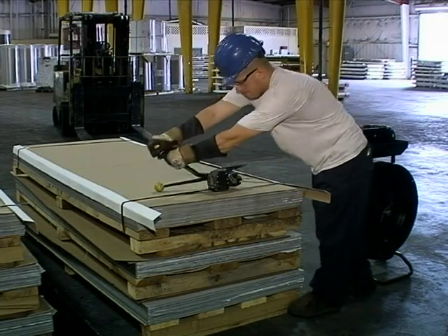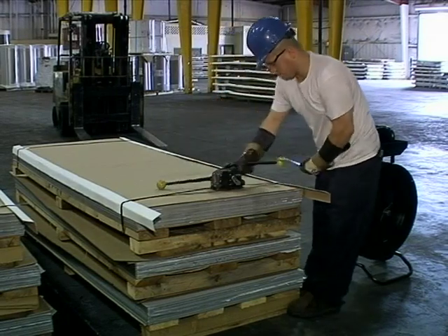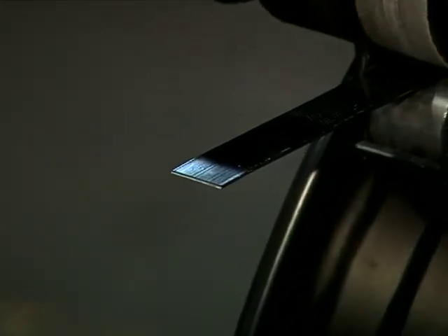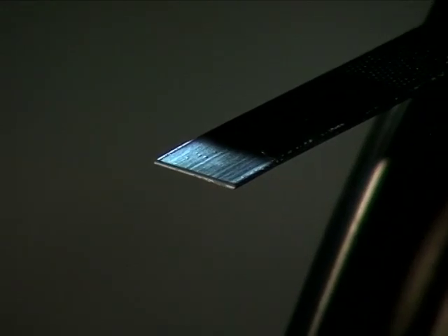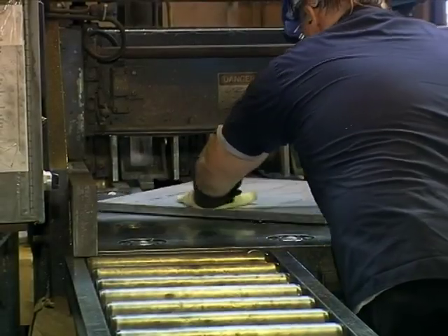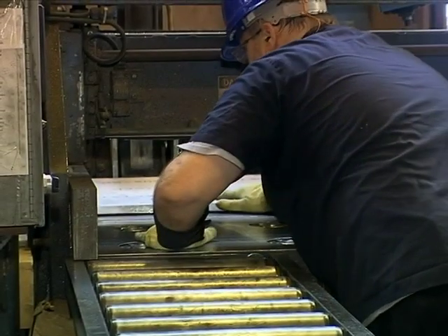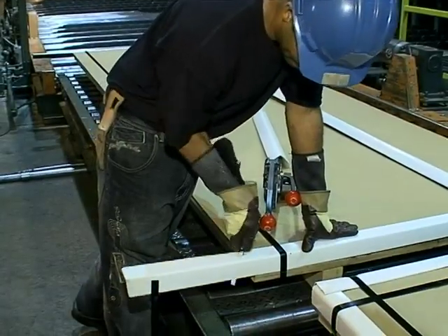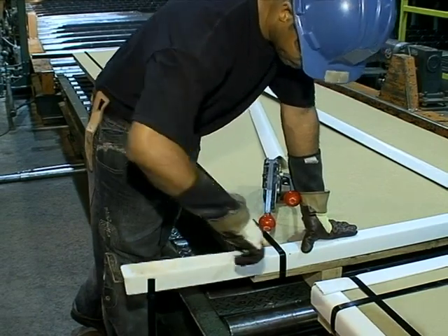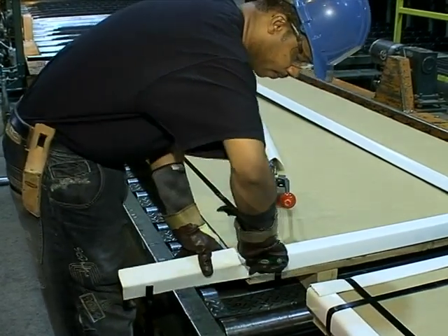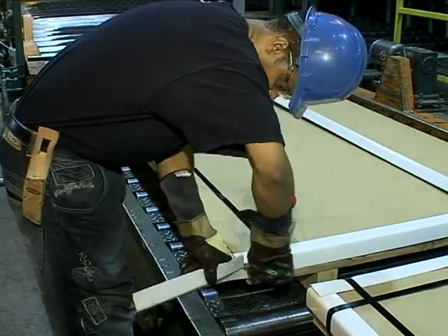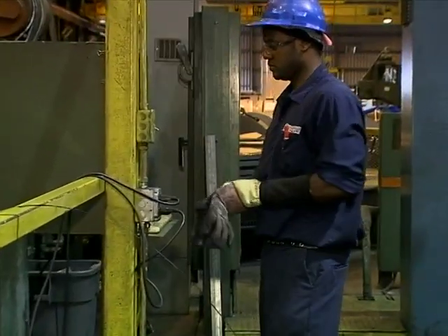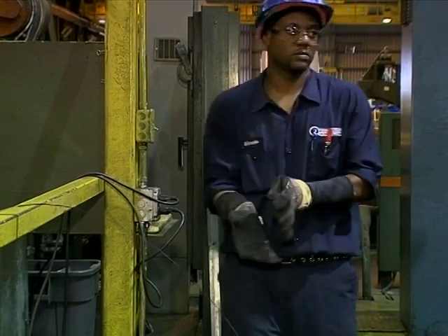Typically, the edges have been rounded by the manufacturer of the banding, but a razor-sharp edge is created when the banding is cut on the end. In addition, laceration risks are present when handling cut plate, long products, or scrap material with rough edges. Utility knives are commonly used on the job, and these too can very easily cause a laceration if not used correctly. If you are performing any of these tasks, it is critical that you wear the proper personal protective equipment or PPE.